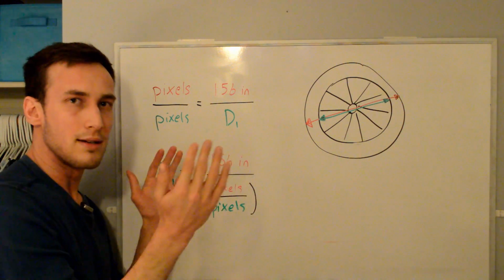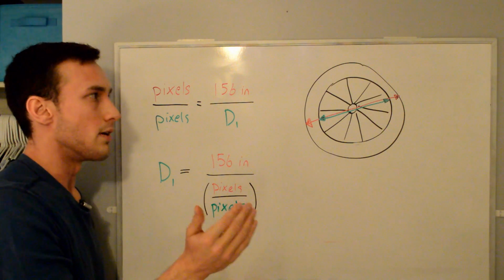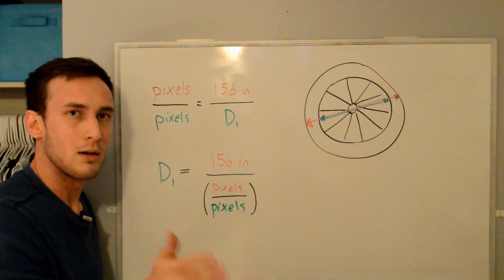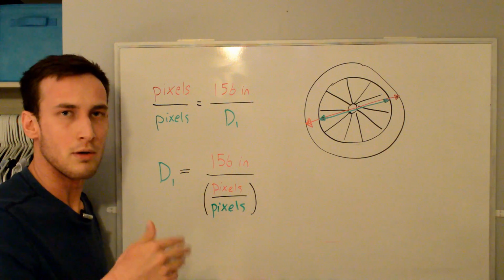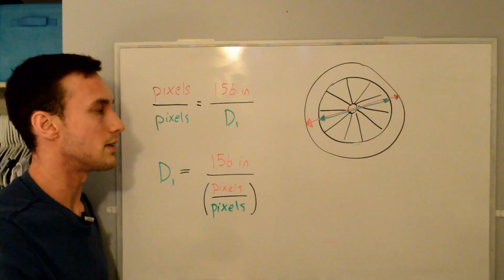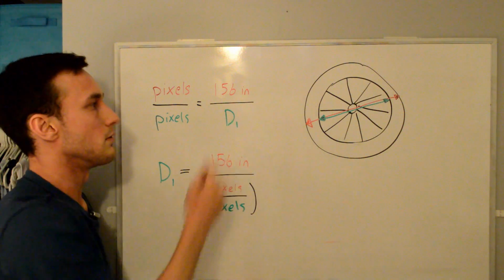And I'm going to take that ratio, and I know that the outer edge that I'm measuring is the maximum nacelle diameter, and that is given in a document that I'll post in the description for airport handling of the Boeing 777 as 13 feet. And so that 13 feet is 156 inches.